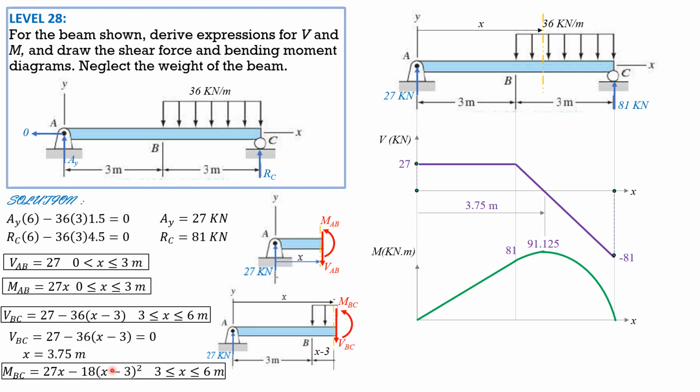If you differentiate this with respect to x, remember it is shear. And if you describe the ordinate of the shear, it is positive and it decreases, from first degree to second degree, until it is negative 81. So the slope beginning here is 27. Here 27 is the slope because the ordinate is 27. Then 0 when shear is 0, horizontal.